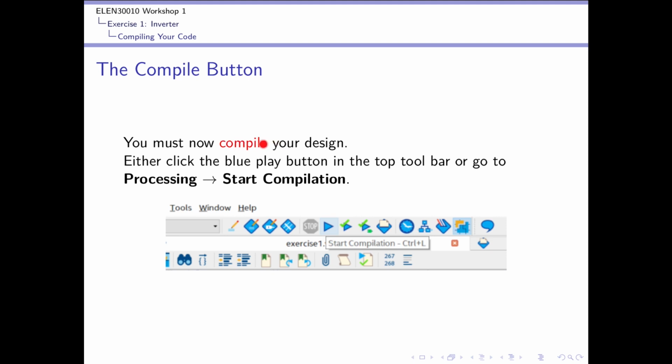When we press the compile button, many things happen. And if you are familiar with how we design normal electronic circuits, then what happens when we press the compile button is going to make a lot of sense. So imagine we're building our own circuit by hand. The Verilog code we wrote describes the circuit we want. Equivalently, we can think we have a schematic in front of us, a diagram of the circuit we want. What we need to do is go and order those components from the shop. We need to physically arrange them onto a PCB, and we need to wire up the components, design the traces